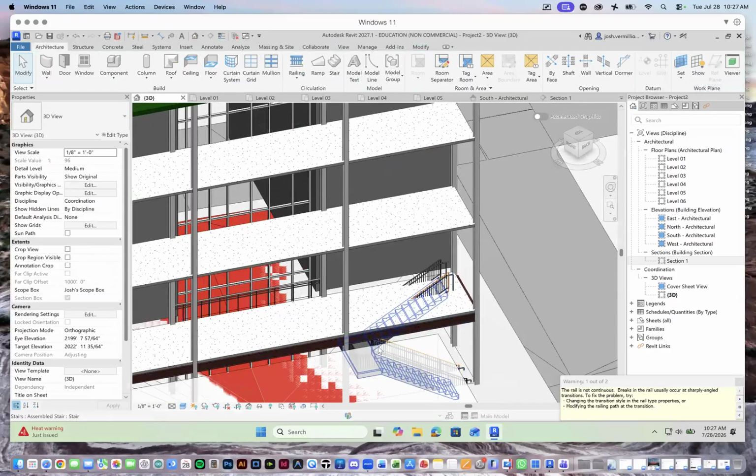What I need to do is actually change the direction of them and then start to slide my floor slab around to meet up with them, right? So I'd probably draw the stairs in the other direction, switch back to here. So anyway, I have some things to do. I'm going to draw the stairs here in a minute. But the other thing is I can also tell it how many floors it goes up so I can create a stair tower.